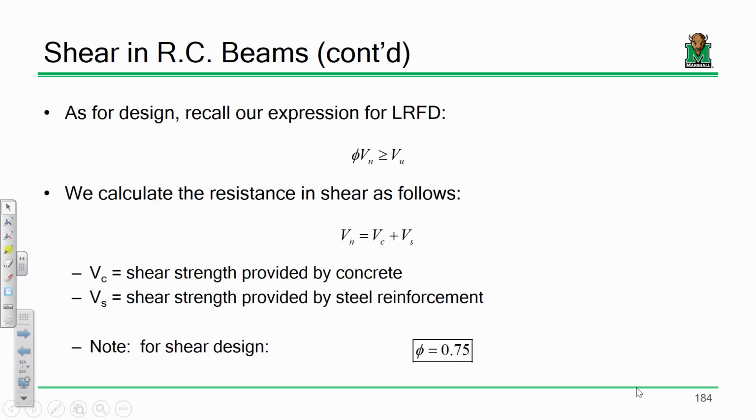So here's the thing. When you have a shear diagram, remember, what is a shear diagram from structural analysis? All a shear diagram is, is a visual representation of the sum of forces in the y direction, right? Remember when you start plotting a shear diagram, you start at 0, and then when it's all said and done, you better end back at 0 in one way, shape, or form. All it is, is just a fancy graphical representation of the fact that equilibrium is maintained, that the sum of forces in the y direction equals 0, okay?